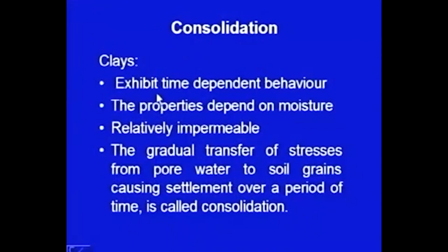Now, I am coming to the next very important phenomenon in the soil mass, especially for clays. It is consolidation. The clay soils exhibit time dependent behavior. What we mean by this is that if you construct a building on a clay soil and if you construct a building on a sandy soil, the settlements in case of the clay soils will be time dependent. They will be increasing with time, whereas in case of the sandy soils, it occurs almost within the time in which the building is constructed.